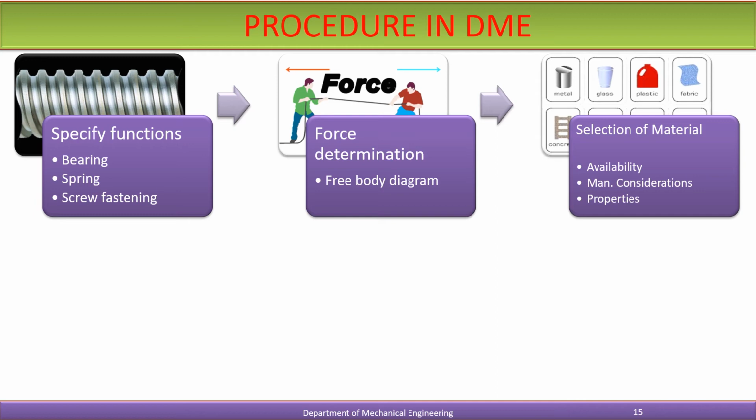That we need to take into consideration. Then selection of materials. The four basic factors which are considered in selecting the material are availability, cost, mechanical properties, and manufacturing considerations. Consider the designing of a flywheel or housing of gearbox or engine block.